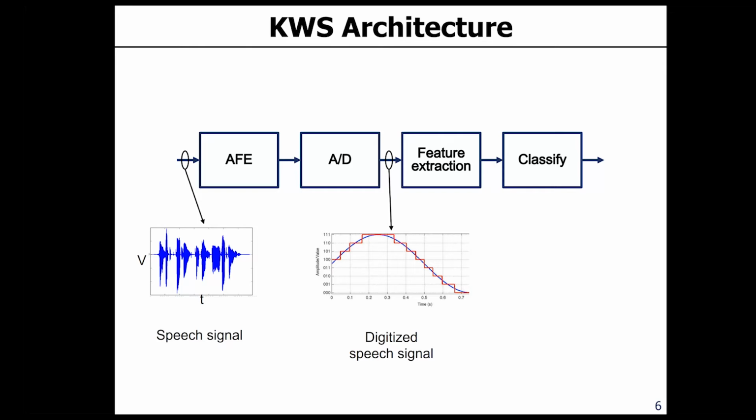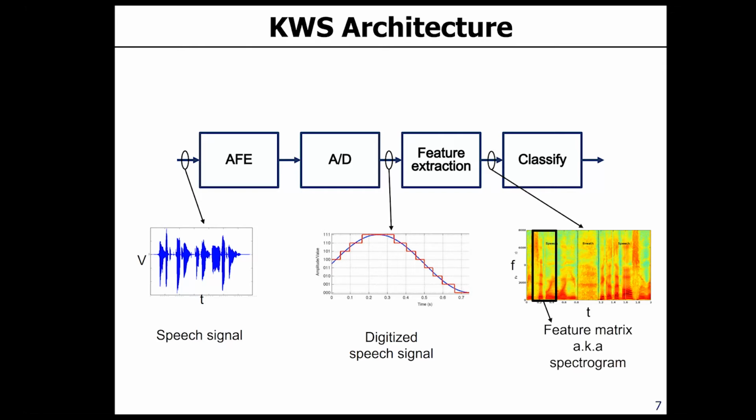And after that, they do the feature extraction. And for feature extraction, the most commonly used method is the so-called spectrogram. A spectrogram is essentially a spectrum transient waveform, meaning the x-axis is the time, and the y-axis is your spectrum frequency component, right? And then what is usually done is, they grab a small box of the spectrogram, the heat map essentially.